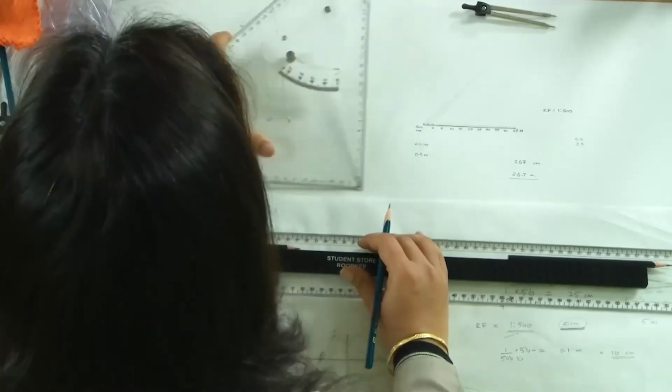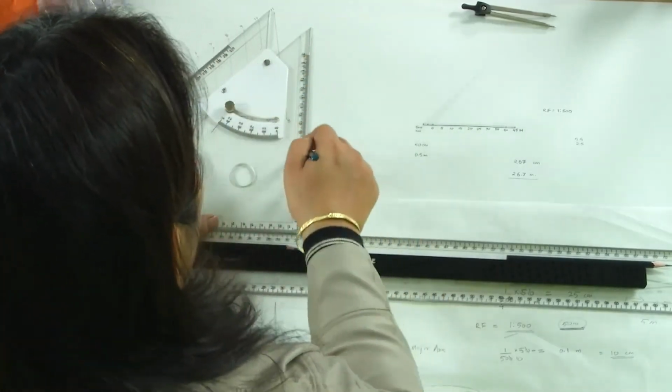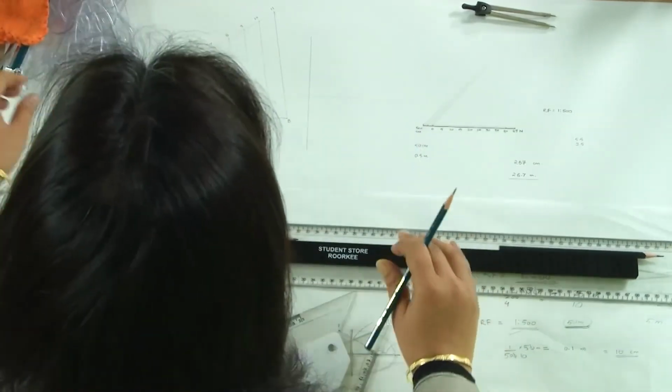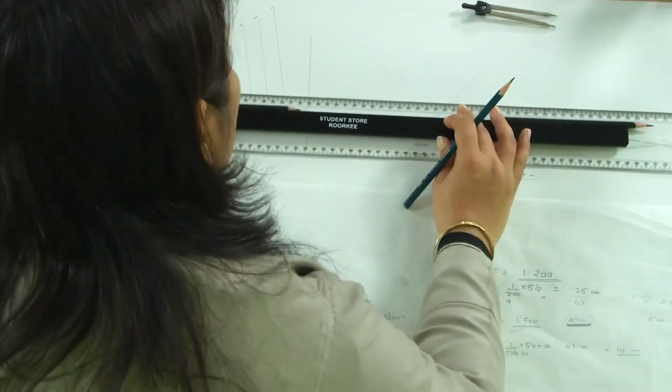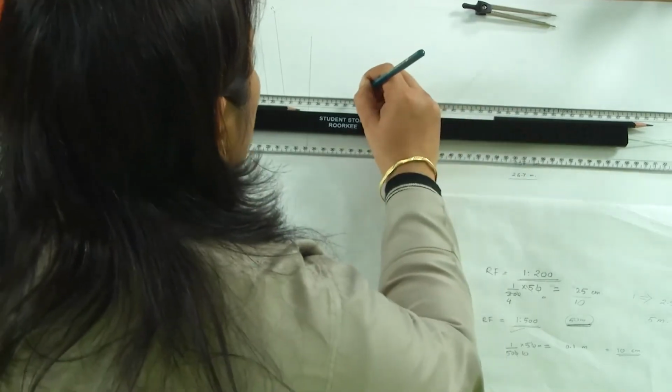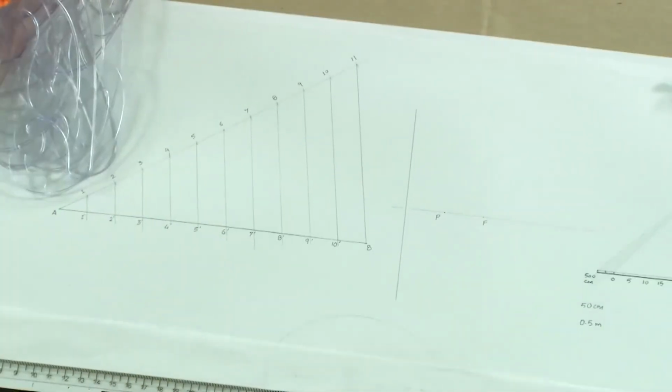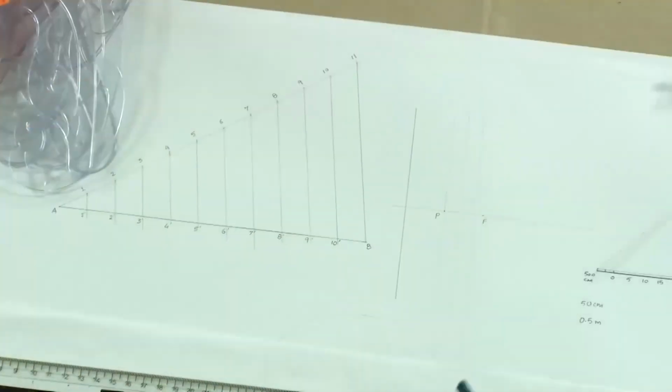So suppose we have a directrix given here. We will just draw a perpendicular axis for a given distance of the focal point, say again 5 centimeters, what we had taken earlier, and the midpoint of that is going to be the point where the parabola will start or meet the axis. This is the focal point. Now what we'll draw here is these perpendiculars passing through these points.